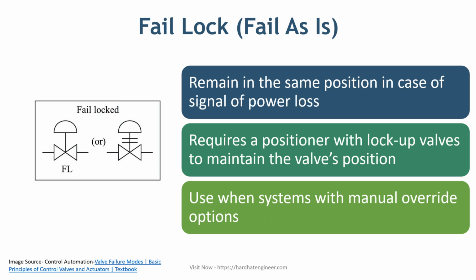Finally, let's talk about the fail lock mode. In this case, when the valve loses power or signal, it stays in its last position, whether open, closed, or somewhere in between. This mode is not shown in the image because it typically requires additional components, like a positioner with lock-up valves to maintain the valve's position.